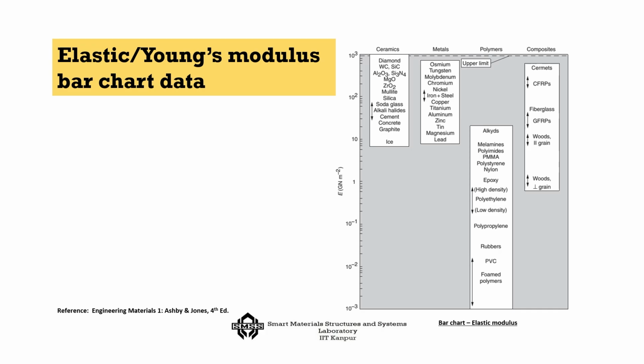So, I will come to it in a minute. So, this is just showing you the modulus of elasticity range that you can expect. Okay. The highest in this direction will be for materials like diamond, tungsten, alumina and all these things. So, that would be the highest, and then of course, the more usable group will be somewhere here. Okay. Iron, steel, titanium, aluminum.